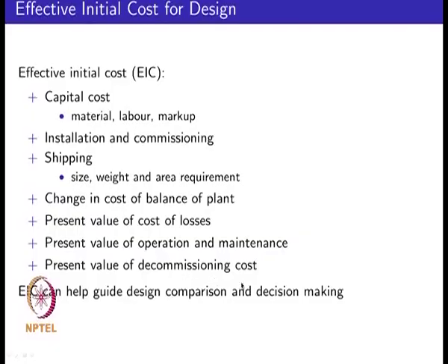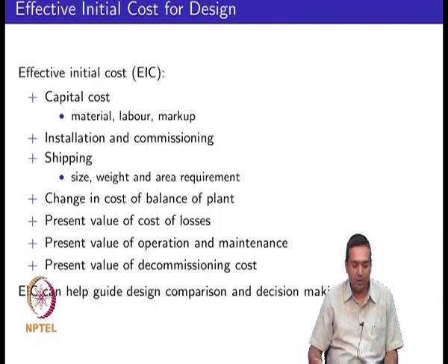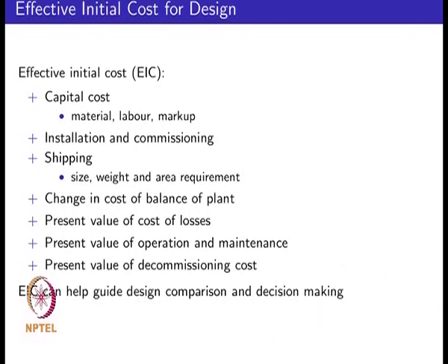At the end of the life of such a system, since you are talking about power equipment, you are talking about longer time frames, maybe 20 years, 30 years, etc., for a large power system. So, you might also have costs associated with decommissioning. If you have electronic things, you might have to look at how to dispose of electronic waste. If you have machines with windings, etc., you might have value in the copper or the iron. So, depending on what the decommissioning costs are, you will have to make a decision, and we will see how all these costs can be effectively rolled up to an upfront number to see which particular design might be more appropriate depending on your application.